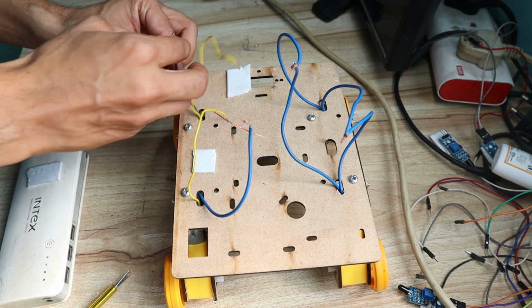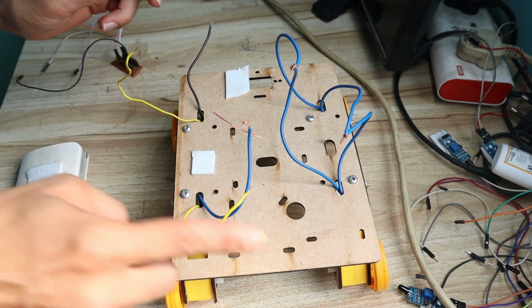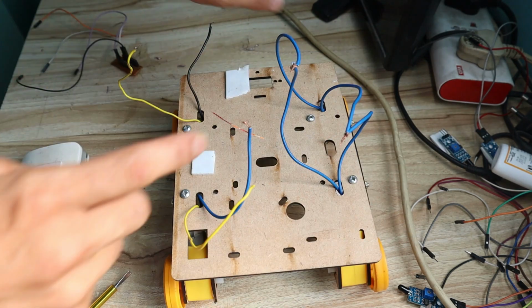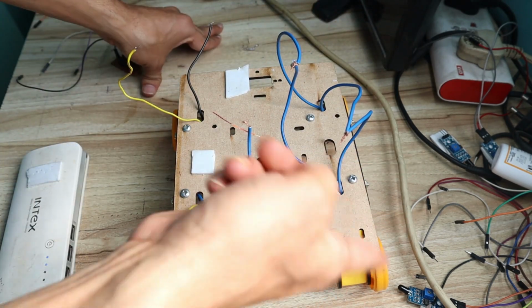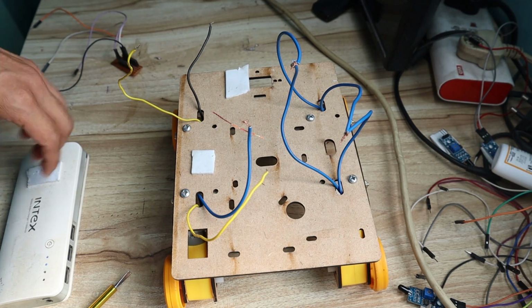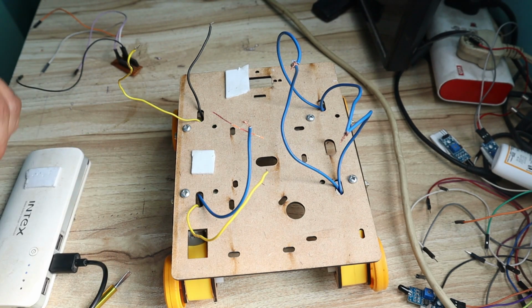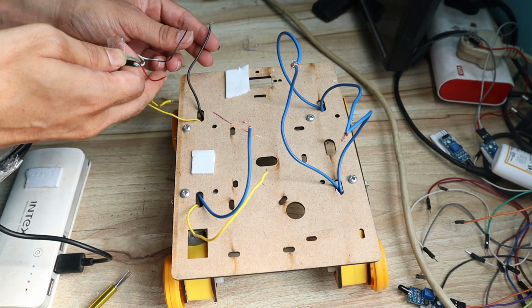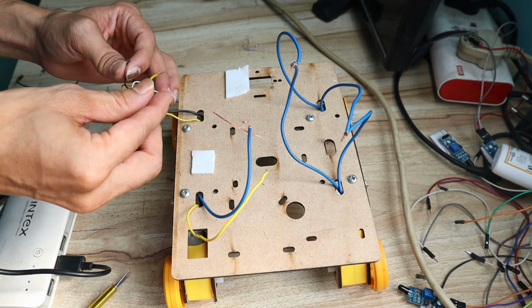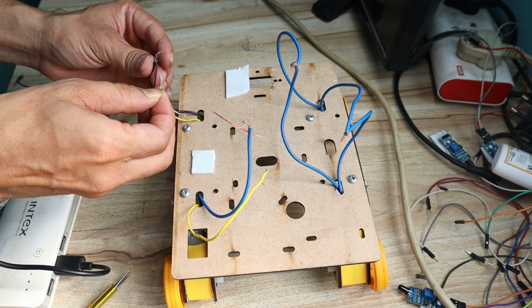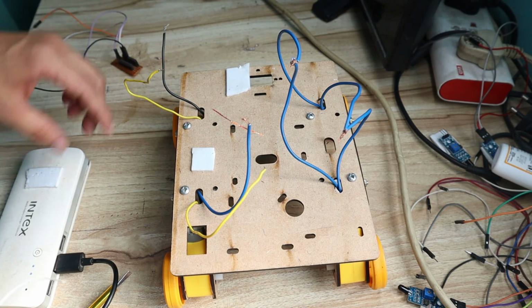Okay, so again I will take random 2 pins from this motor. Now we need the negative direction, like this side direction we require. So the motor should rotate in anti-clockwise direction. Again from the power supply I will take random 2 pins and connect here. Okay, now I can see my motor is rotating in anti-clockwise direction.